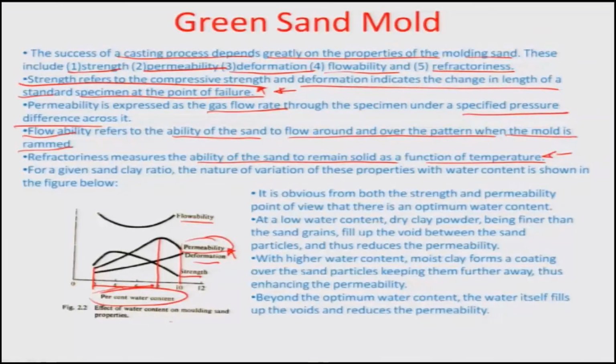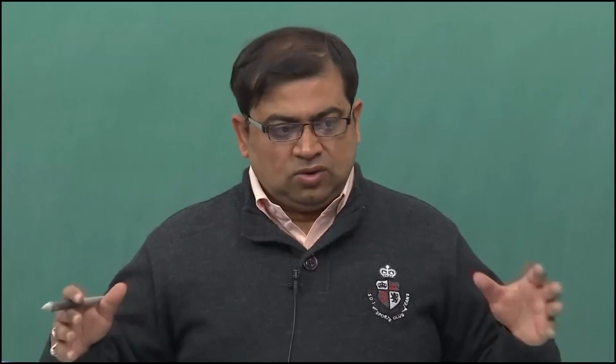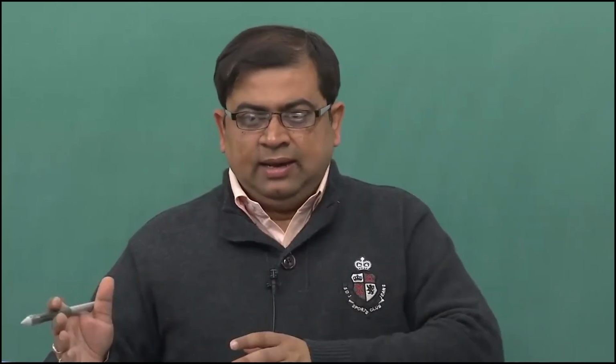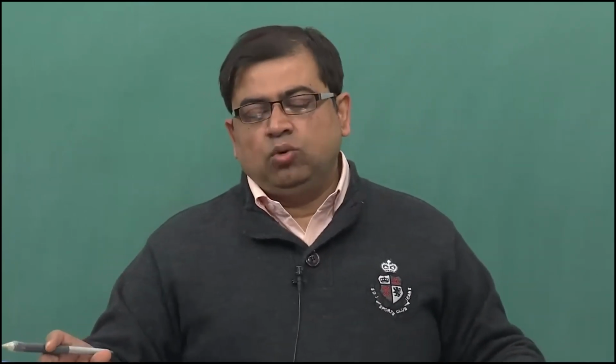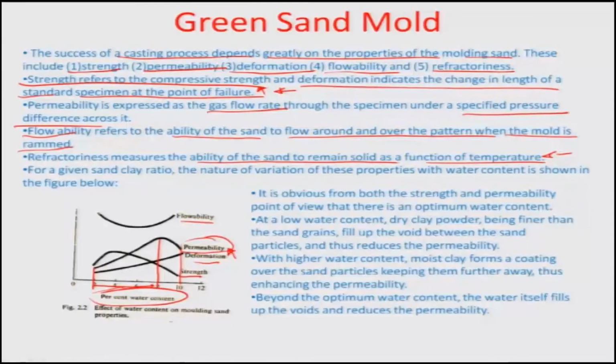This is a very important aspect, and similar explanations are available in the literature for flowability, deformation, and strength, based on this concept of loose clay powder, coated clay powder, and additional water in the different voids of the sand mold. So, in the interest of time, I would like to end this particular module.